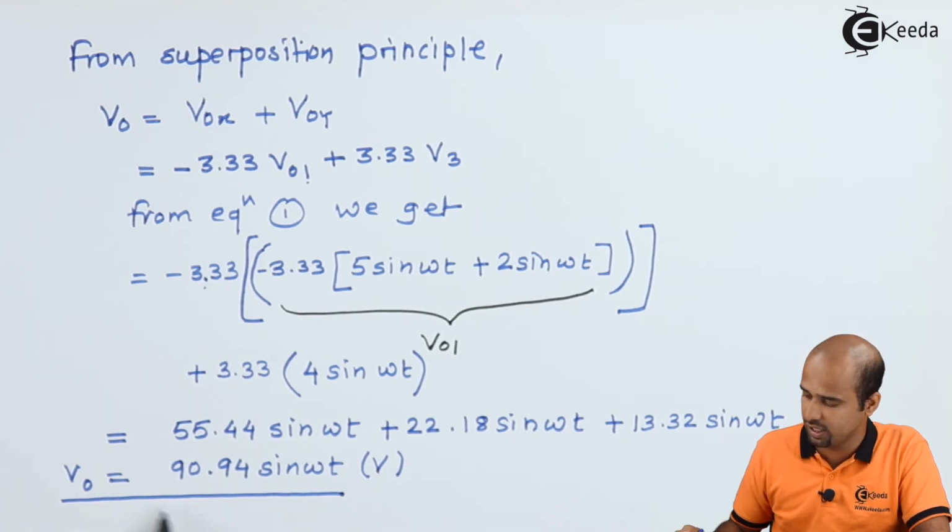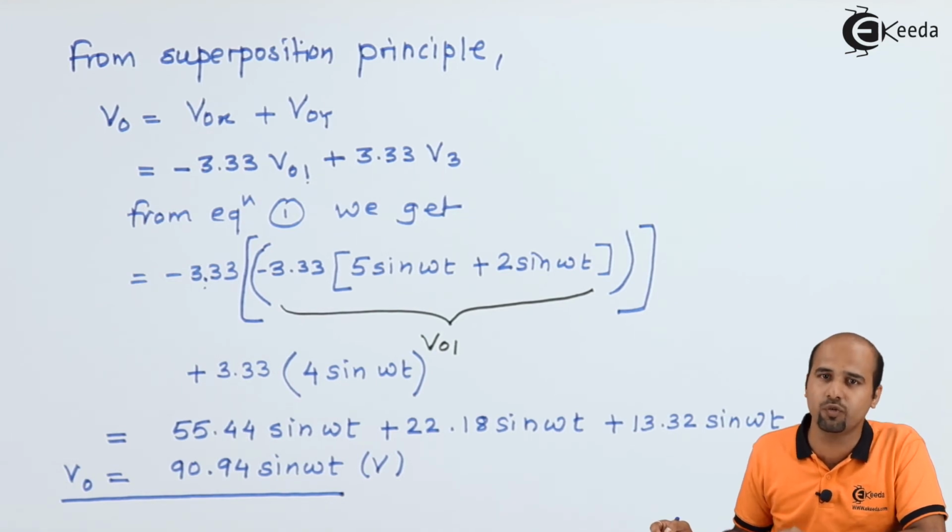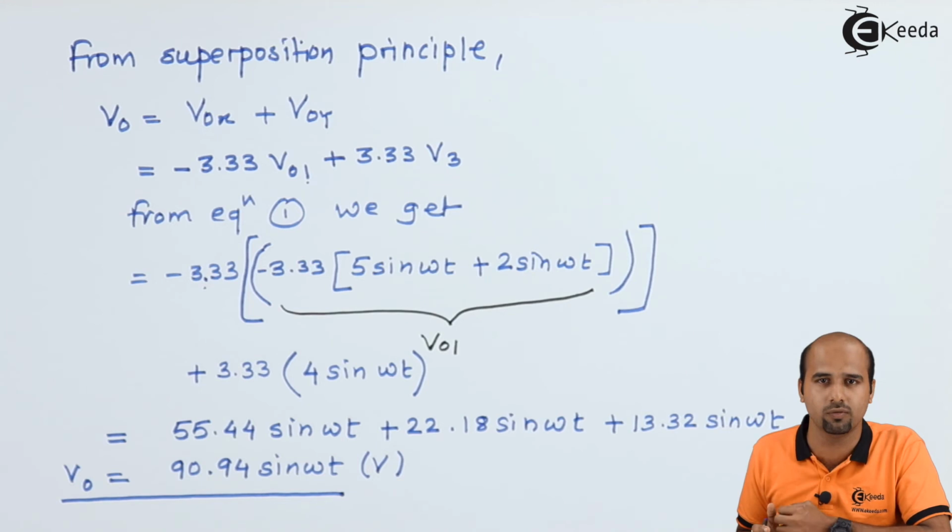That means somewhere in the AC signal I will get clipping well above the 14 volts, right? So we have to write the comment in your answer itself. Your waveform will get clipped off and we will not get proper amplification. In the question itself they may ask you whether it is possible to get the amplification in this particular circuit, yes or no. So your answer is no. This is because we will not get full swing, we'll get the clipped waveform.